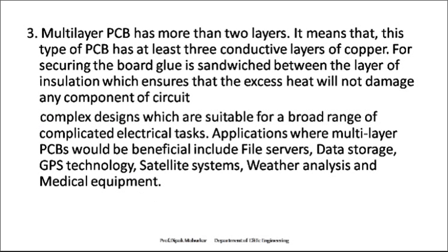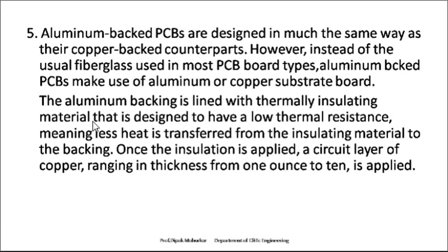Then we are moving to the next, that is nothing but aluminum backed PCB. They are designed in much the same way as their copper backed counterpart. However, instead of the usual fiberglass used in most PCB board types, the aluminum backed PCB makes use of an aluminum or copper substrate board. The aluminum backing is lined